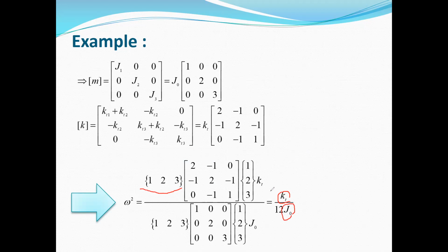By using the analytical method, you can extract the natural frequency for this system, and you can compare it with this system because you have the matrix M and K. So if you form the matrix K minus matrix M times omega squared, and for example, we call it matrix C, the determinant of this matrix must be equal to 0.